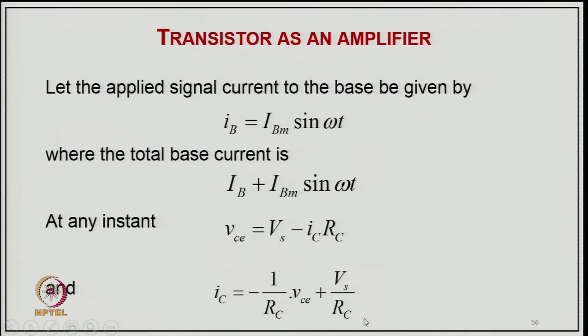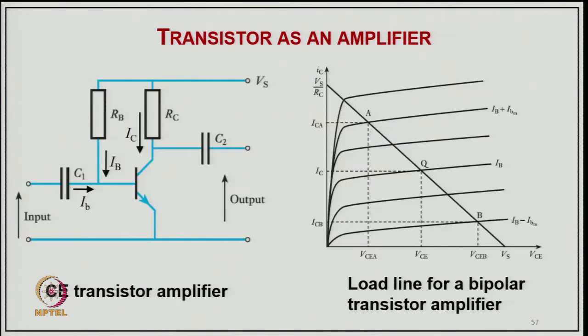Here also you are providing a kind of DC bias, and you can just see the same circuit here. You have a bias at the base which gives you a DC component, and on it comes an AC component. So the transistor is always biased in the unidirectional mode as far as operation is concerned, so that it works as an amplifier. Here you are getting an amplified voltage, but this capacitor blocks the DC voltage.